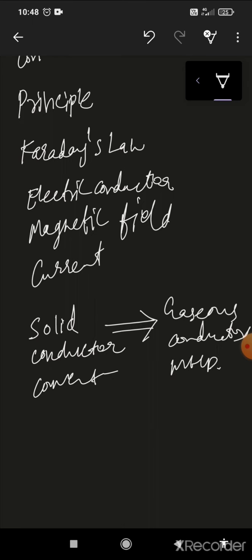What is this conductor? It is an ionized gas. If such a gas is passed at a high velocity through a powerful magnetic field, a current is generated and can be extracted by placing electrodes in a suitable position in the stream.